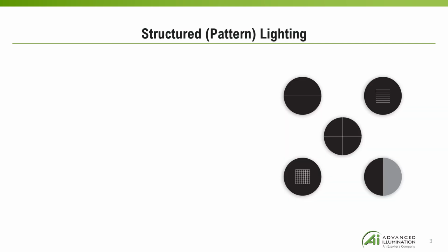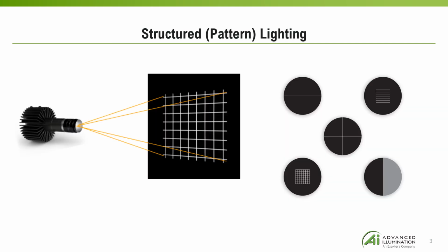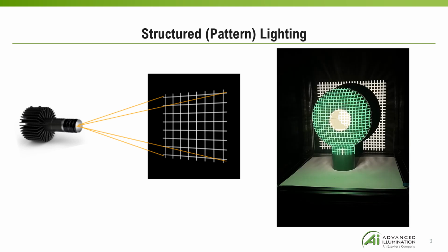Pattern lighting is a technique in machine vision where a known pattern of light is projected onto an object or scene. The way the pattern is deformed on the object's surface reveals information about its 3D shape. A camera captures the deformed pattern, and this information can then be used to reconstruct a 3D model of the object. Software algorithms analyze the captured pattern and extract the 3D information. This style of LED pattern lighting was designed as a cost-effective and safe alternative to laser lighting.